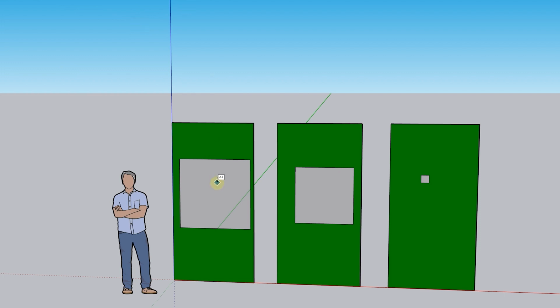So we're going to start with the one that is 20.9 ACH 50. That's equivalent to 12.15 square feet. Next one is 13 ACH 50, and that's 7.71 square feet. And where we finally got, after we added all the liquid flash, we got down to 0.3 ACH 50, and that's the equivalent of having around a 19-20 square inch hole in the house. So again, it's a lot smaller, and we're trying to keep it smaller than that.